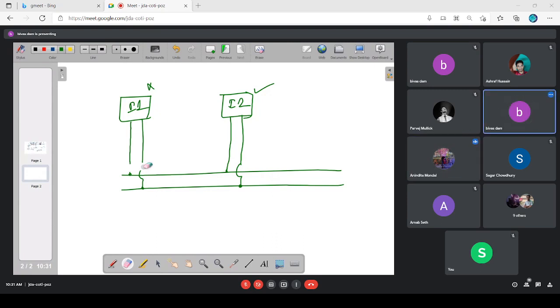So only when I2 is enabled, remember that the address bus will contain only one particular address, and the address is specific for every device. So if I place the address corresponding to I2, that means I1, I3, I5, I4, I10, I100, everything is disabled. Only I2 is enabled.